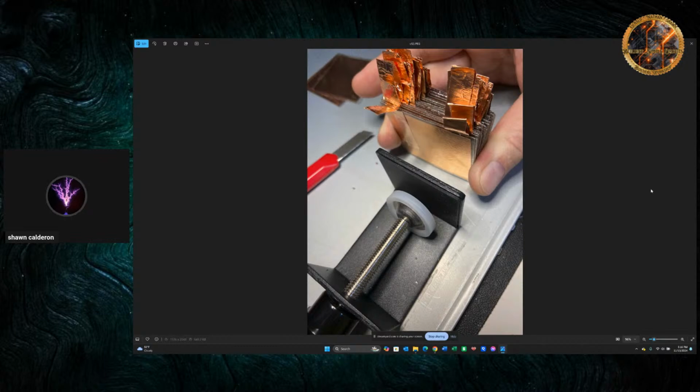All right, so you see them stacking up here. Now they're getting ready to go in the clamp. The clamp really helps the plates get even closer together. There are 3 things that improve capacitance, and capacitance is just the storage ability to hold charge. One of them is the dielectric. Mica is a great dielectric, so that's what you want to think about in a capacitor to improve capacitance.